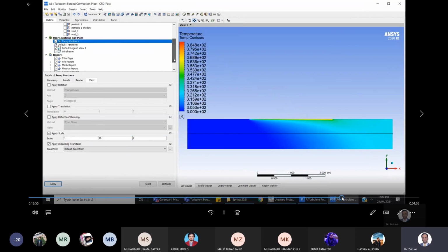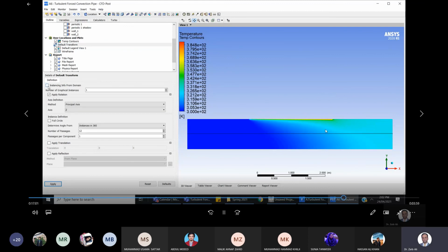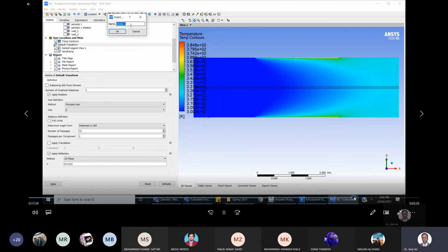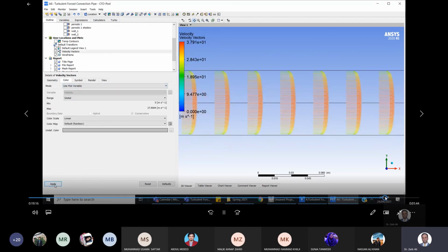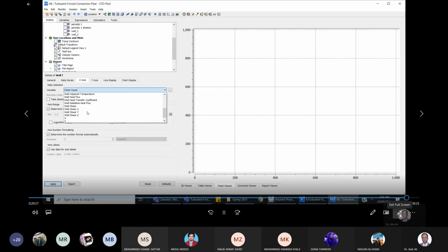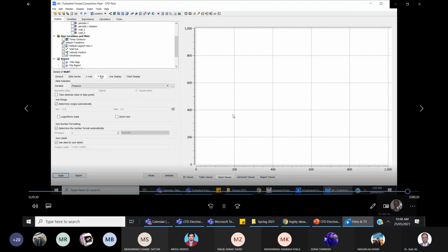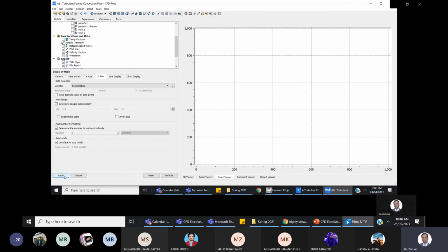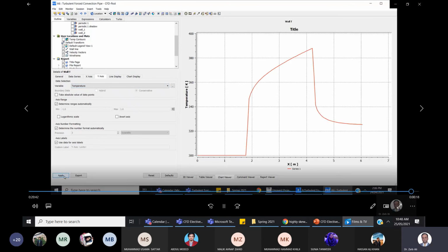And then you run the simulation, and then you can observe the effect of that heated region. So here we have various contours, temperature contours, velocity contours, and so forth. You can also visualize the upper wall temperature plot as well. So you see that insulated section, and then in the heated section we have a gradual increase in the temperature, and then in the rear insulated section we have a gradual decrease.